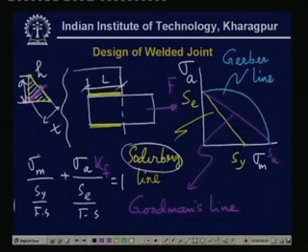Remember, sigma m is Fm divided by the total throat cross sectional area, and Fm is known. We want to calculate AT. So, here we replace sigma m by Fm divided by AT. Once you substitute Fm by AT in place of sigma m and Fa by AT in place of sigma a, then this equation gives the unique value of AT.